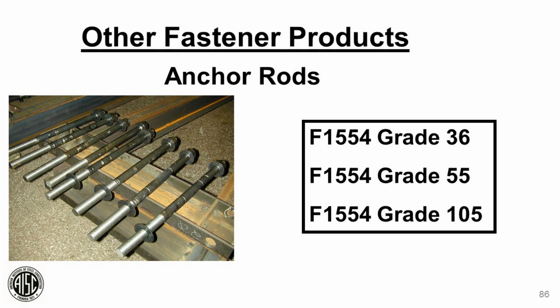And can you say whether it's possible to add that supplement to grade 105 anchor rods? No, it is not. If you read F1554, the supplement is only available to grade 55. It's not available to grade 105, which means 105 is never weldable. So keep that in mind. If you specified F1554 grade 105, it will not be weldable.